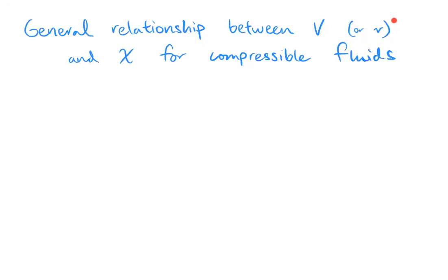you're going to have to use a stoichiometric table and then think about mole fraction and be able to relate what was your initial volume to your final volume, or what was your initial volumetric flow rate to your final volumetric flow rate. So I want to make you aware of the pattern and get you thinking about these cases more generally. And just like earlier in the course, we went over this generalized stoichiometric table. Here we'll go over this general relationship between volume and conversion.